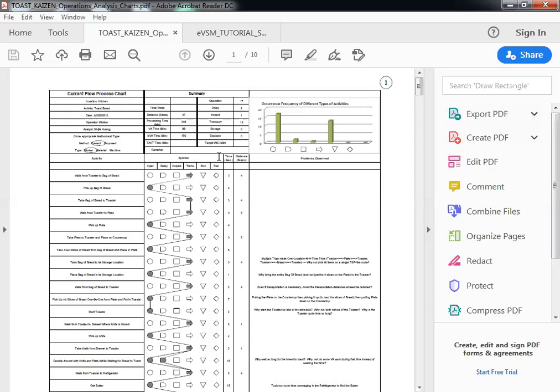Now go back here. Remember we did value stream mapping? So do you see that compared to value stream mapping, this classical industrial engineering chart is not that good at recording all the data. So there are two challenges. One is that when you have an operation step, you would like the data columns to be changeover time, cycle time, first time through, quality, uptime of the process, right? Number of operators, is it semi-automated? So these two columns are really not capable of capturing that information.